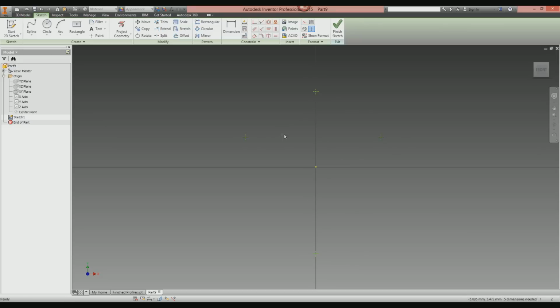Right, well, what next? Okay, well, the next thing I want to do is make sure that these points are symmetrical around the center line. How do I do that? Well, you could just create a dimension, say maybe make a dimension from there to there, say make that 10, and then put another dimension there of 10 and then make another dimension from here to there is 10. But that's not really best practice.